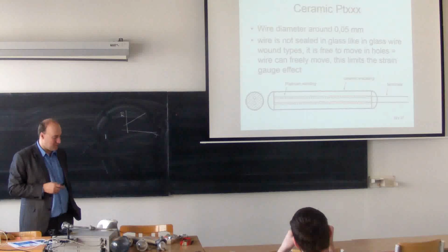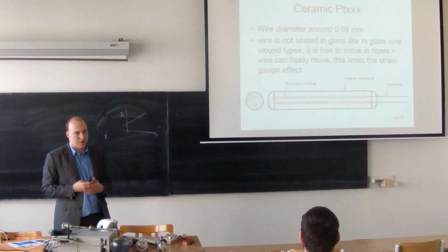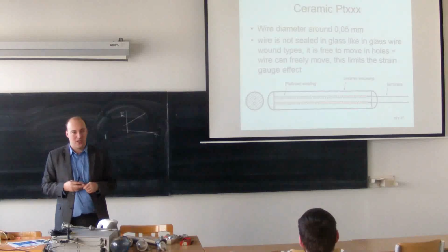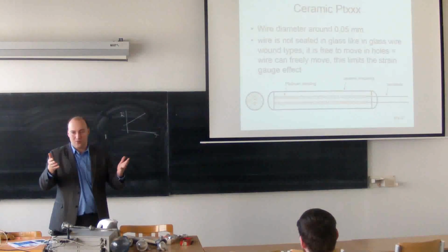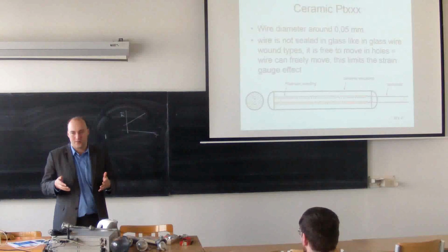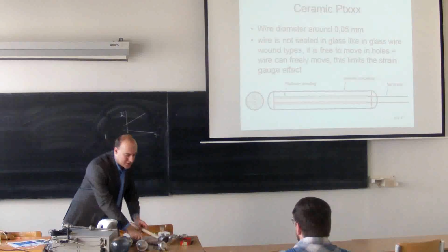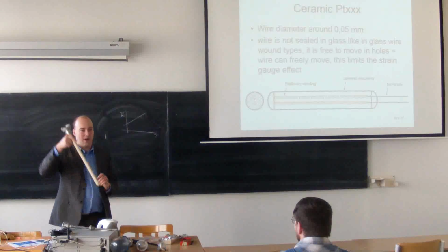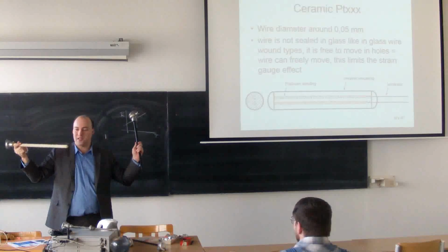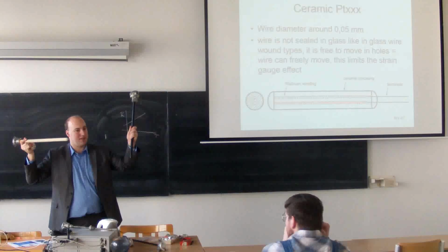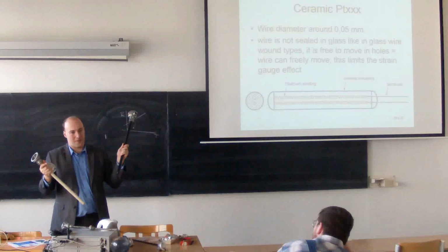But in all cases, we have to protect the sensor from mechanical damage. So in all cases, we will not submerge the PT100 sensor directly into some tank with some material, but we will protect it with something that is called a thermowell. This is a thermowell, and this is a thermowell as well. We'll discuss thermowells next week, but it's nothing other than a pipe closed at the end. The sensor is inside.